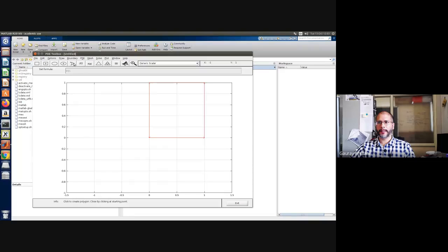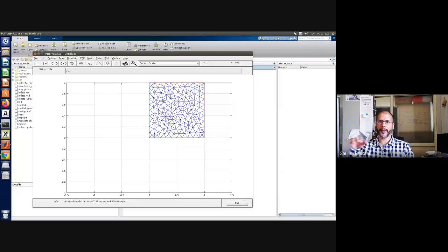All right, so this is the equation we want, and we have defined the equation. So you can see that I'm following these steps correctly. After the PDE, the next step is to initialize the mesh. So I can just press it, and it has automatically created an unstructured mesh here. Earlier I drew a structured mesh for you, those rectangles, but now it's unstructured. It's much easier if you have an arbitrary shape domain. You can define an unstructured mesh which fits quite well with arbitrary shape domains.